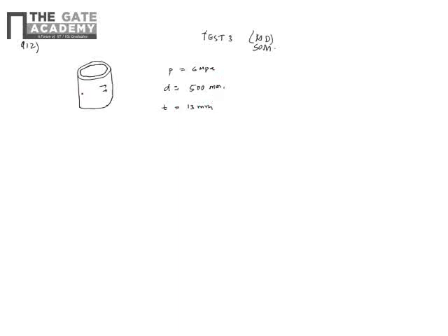Okay, now if you take any element on this, you have the circumferential stresses, basically the hoop stresses, as well as the longitudinal stresses, because the ends are closed and the fluid enters from the opening somewhere in the circumferential location, but the ends are closed unless otherwise specified. So you have these two stresses that is set up on any element, the circumferential stresses and the longitudinal stresses.